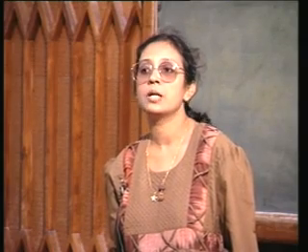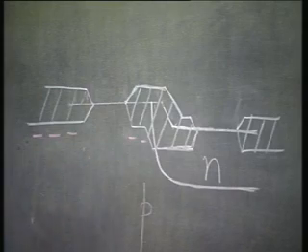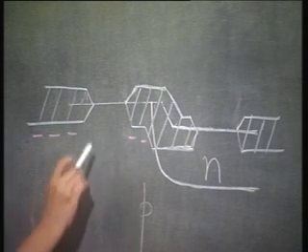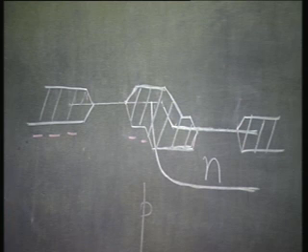Now, in the next step, you again do a nitride oxide mask step, but this time in order to define the active transistor regions. With these masks in place, you carry out the field oxidation, but prior to that you do a channel stop implantation. Now, you do the field oxidation. So, you see apart from the active transistor region, the rest of the surface is protected by thick field oxide.